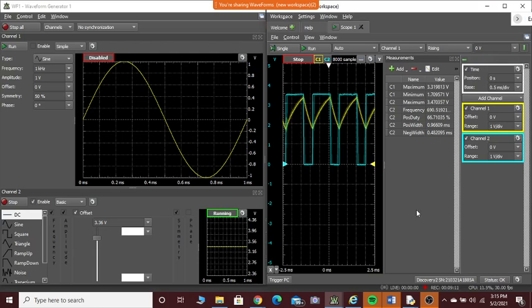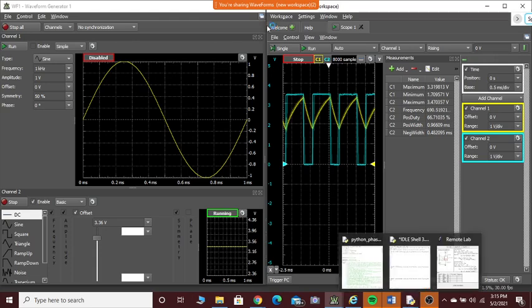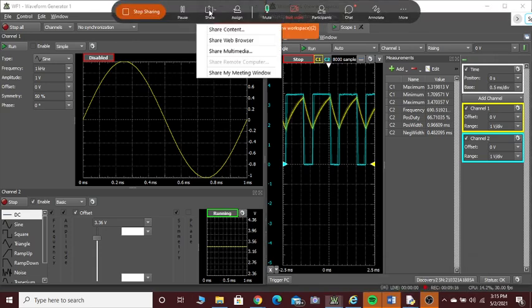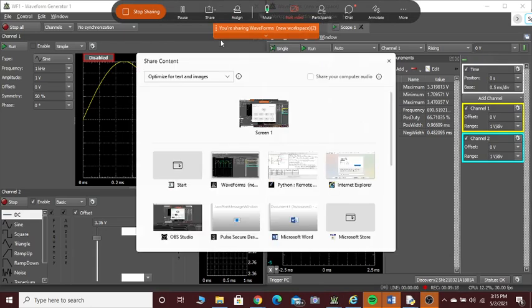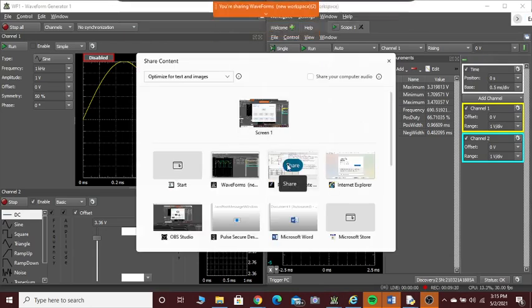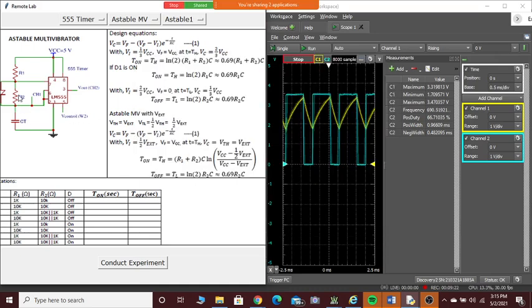Because when I say R2, let me also share that circuit diagram. Where is my circuit diagram? The circuit is here. Can you see it only depends on R2, CT, and of course this one? There is no question of the external voltage. Only T on keeps on changing. Once T on changes, frequency will change and T will change. Correct?